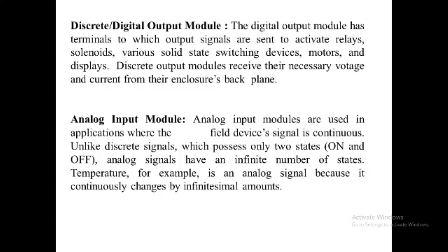The field devices which the discrete output modules interface with differ in their voltage requirement, and this voltage requirement means 120 volt AC or 12 volt DC, whatever the requirement from the consumer side. Therefore, several magnitudes of voltage are provided to control them, and the AC output circuit consists primarily of the logic and power section coupled by an isolation circuit.